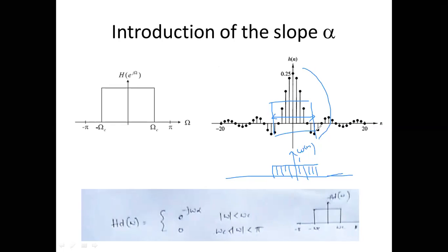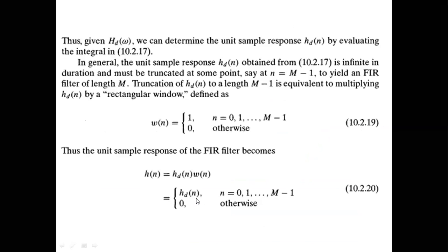So this entire process of picking finite values from the impulse response is called windowing. That's what the author refers to. Once you move the impulse response to the right side, you multiply it with this function w of n. This is what I was talking about, windowing. It will be 1 in that particular duration where you want to pick the impulse response as it is.